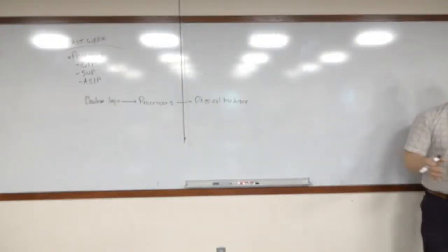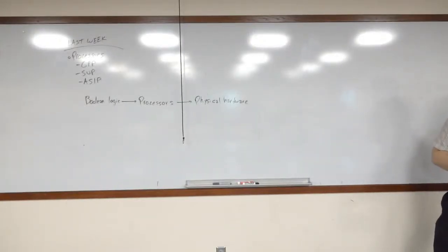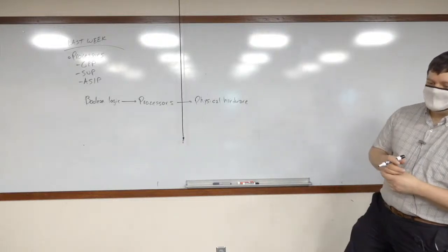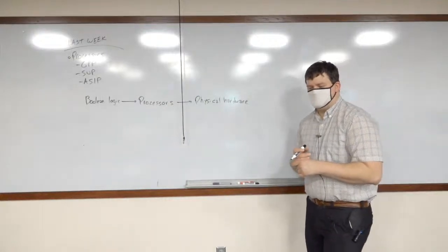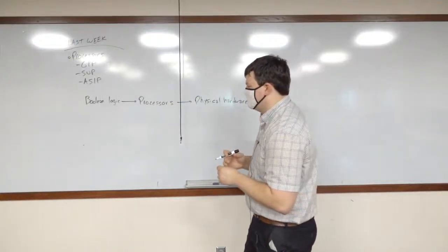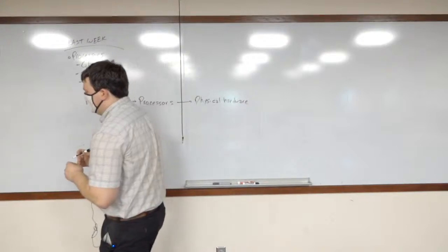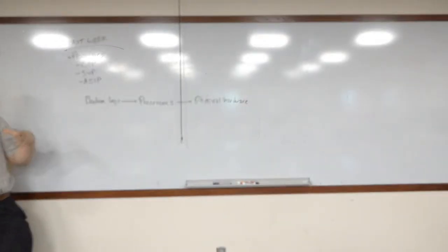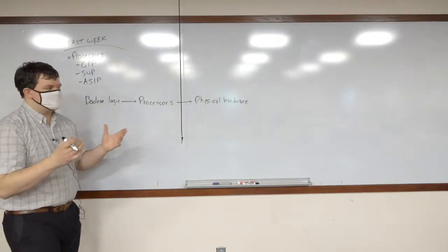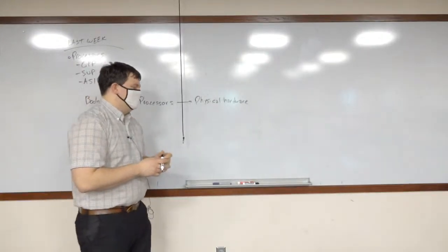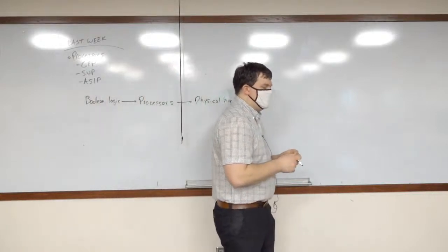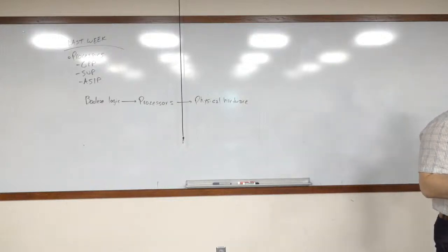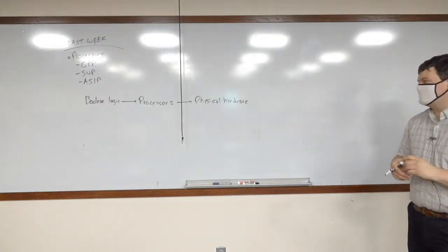It can do I/O. It can do PWM, for example, on the Raspberry Pi. But it can't do an analog output. That requires a separate chip, a separate system. There are some things that processors can do, but they require external componentry in order to actually operate.